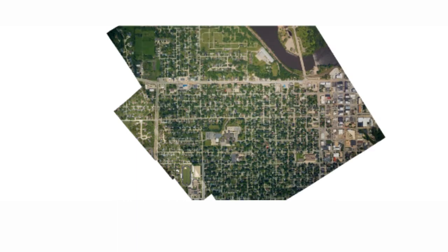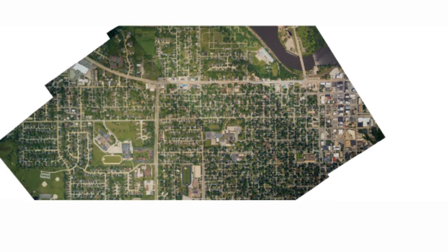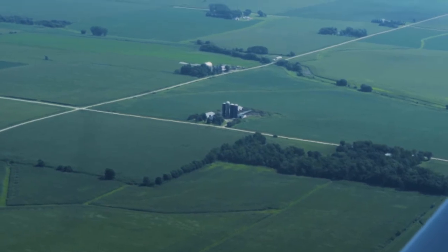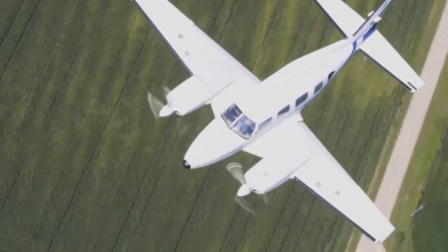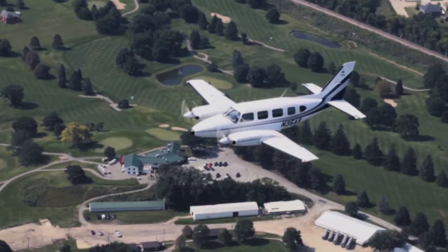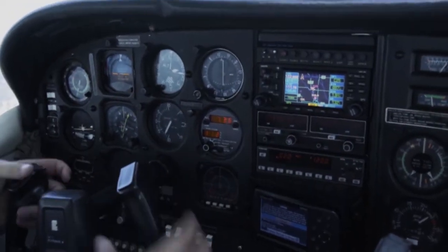We also have beyond 350 megapixel sensors, so there's fewer frames and less computational power needed to process versus UAS. One 350 megapixel frame is easier to process than 10 overlapping 35 megapixel frames. We don't need any additional overlap to build a 3D surface to orthorectify the imagery like unmanned systems do. Altitude is unrestricted, so downsampling isn't needed. We don't have a 400-foot ceiling. We can typically fly as high as we need, just depending upon our aircraft. And that lets us be more efficient.